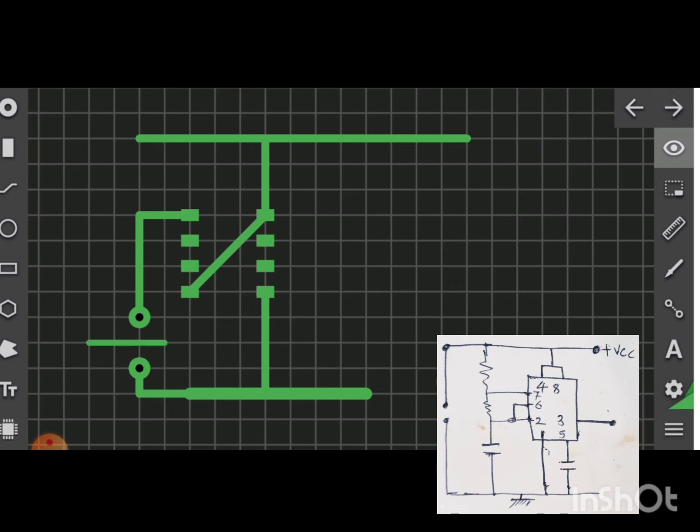We'll go ahead and take some tracks. You see 6 and 2 are shorted, and a resistance connects between pin number 7 and VCC, and between 7 and the shorted point of 2 and 6. So we have to take care of it. Let's say pin number 2; this way we will short and take it. You can take the tracks between the capacitor, below the resistor, transistor, IC, etc., but the gaps should not short. See, it's connected to pin number 7. Pin numbers 6 and 2 have been shorted.